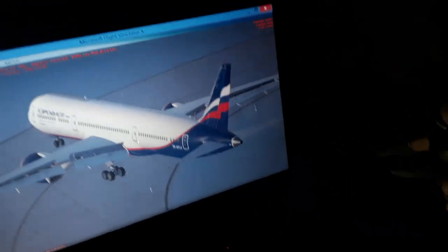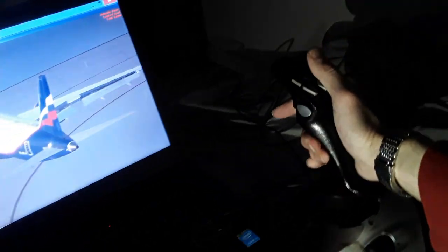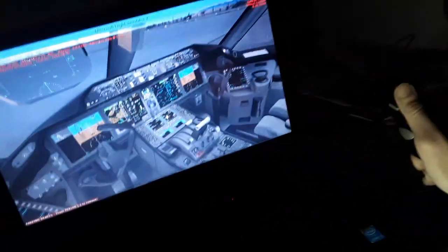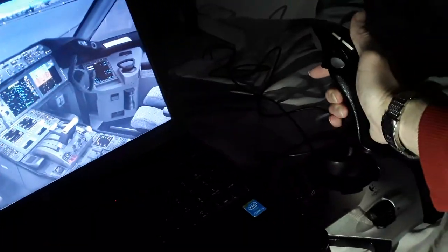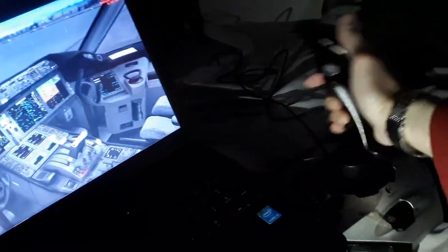And we also have one more axis here, from the nose wheel to the tail of the aircraft, the longitudinal axis, that transverses all the other axes of the flight control. So this is left and right: the side stick in the Airbus, the control column in the Boeing, left and right over here, as you can see. Left and right is the ailerons and the spoilers, the longitudinal axis of control in flight. So you can make left and right turns like this.